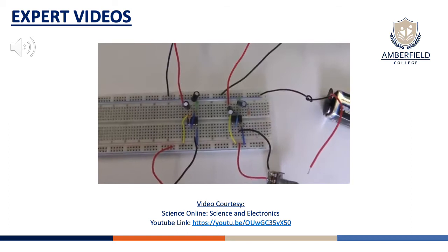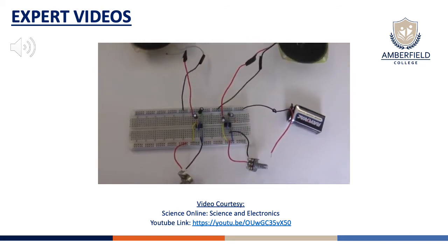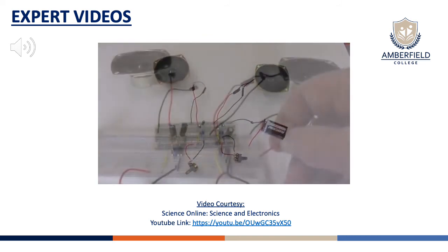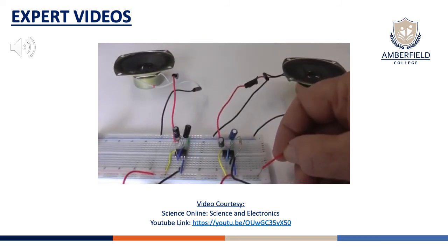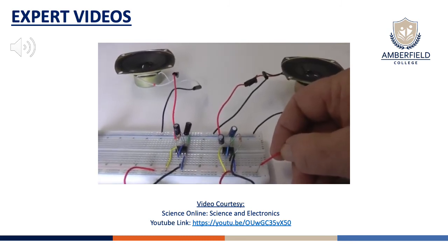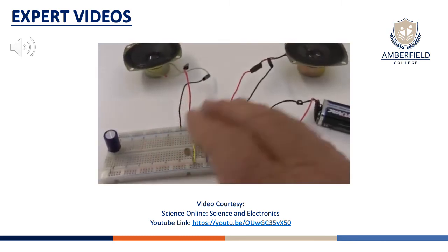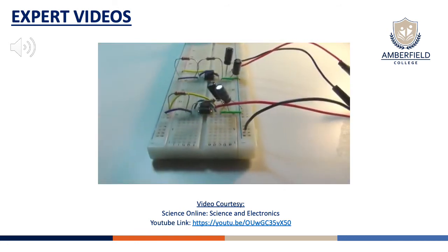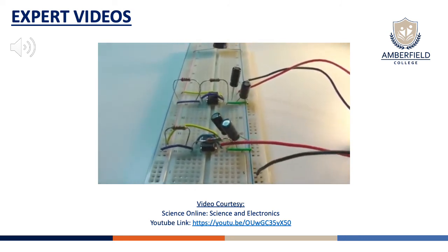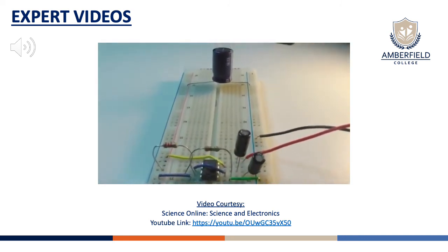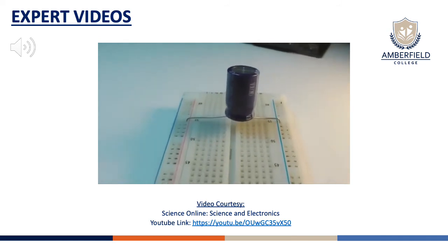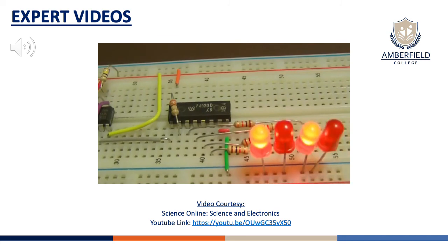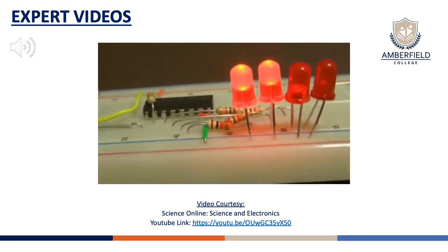Build 2 identical circuits and you will get some richer sounds, a result of the harmonics and beat notes that come from blending 2 different frequencies. If you build 2 circuits on the same breadboard, you may have to connect a large capacitor across the power supply lines to filter and stabilize current delivery to the circuits. Building and experimenting with circuits like this is good training for a career in electronics or computer engineering.